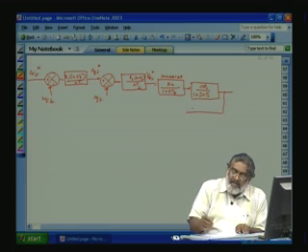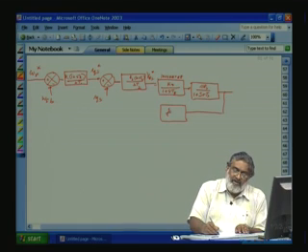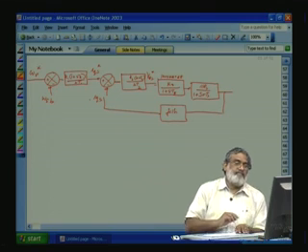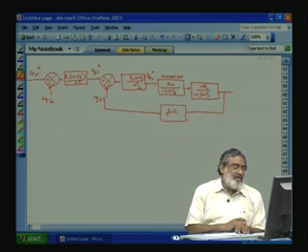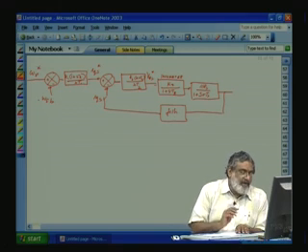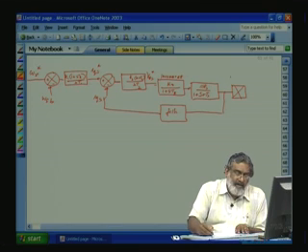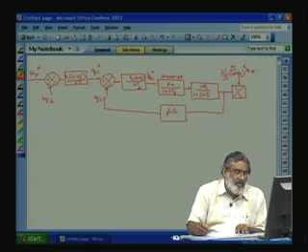So IQS, maybe gain and filter if it is required, you have to put it here and feed it here. So this current control we can design same like a current loop and outer speed loop. So this IQS multiplied by 2 by 3, M by (1 plus sigma R) into IMR is our torque.